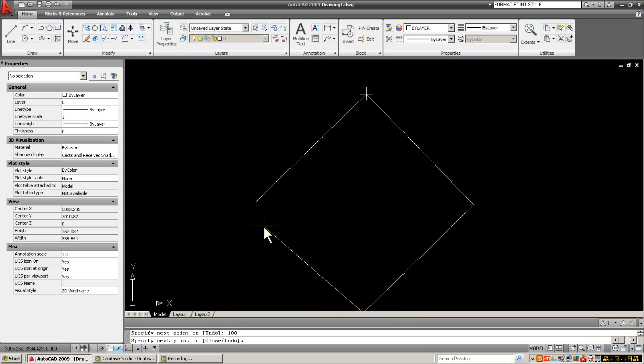Alright, now let's just say that we come back here. I just want to show this idea of misclose. So let's say, for instance, on this particular instance, the bearing that we get back there might be 315 degrees, 45 minutes, 45 seconds, because we should have closed our bearings.